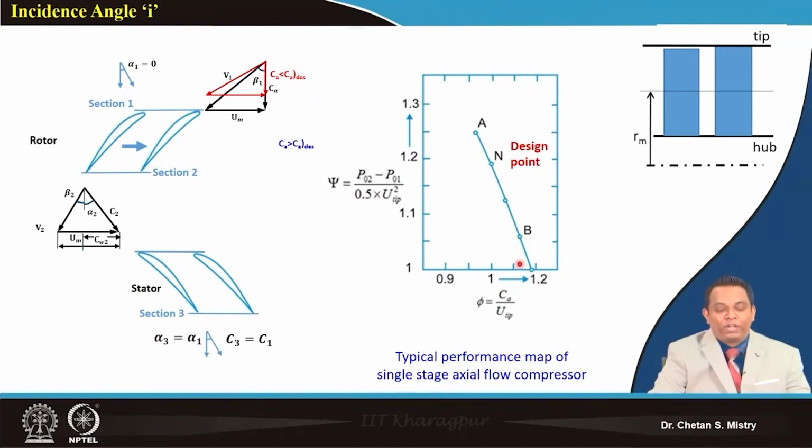If I put that in, this will be the change of my velocity triangle. Remember these things, this is very important. In this case, we know the characteristic of our compressor is that with decrease of my mass flow rate, my pressure will be rising. Now we have represented this in terms of my velocity triangle.